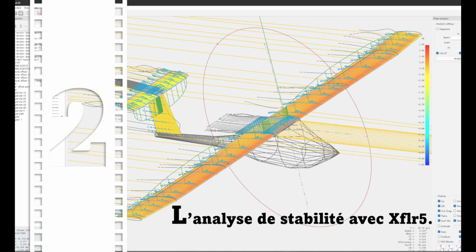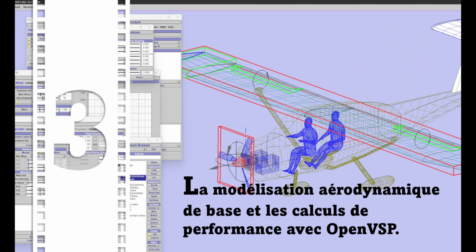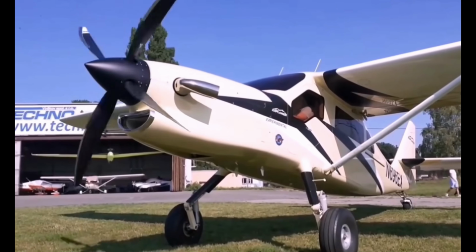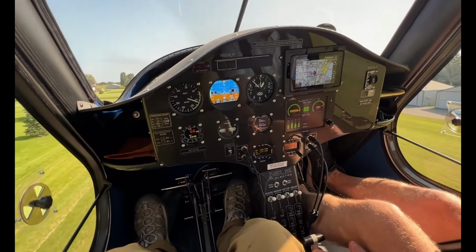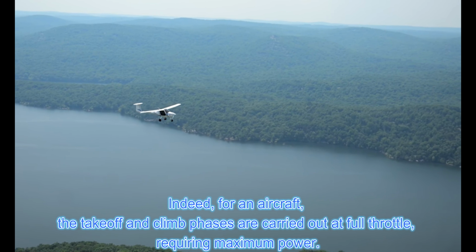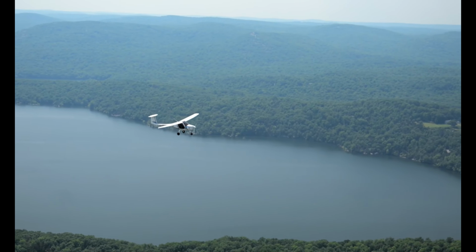After defining the overall aircraft model, it is necessary to determine the propulsion core, the propeller. The size, number of blades, and degree of twist directly affect the power delivery capability. In the video Conversion électrique des petits avions, I confirm the use of Pipistrel's electric motor and its dedicated battery, with a specified maximum rotational speed of 2,500 revolutions per minute. I will use this standard as a reference to evaluate whether the aircraft can meet the takeoff performance requirements.